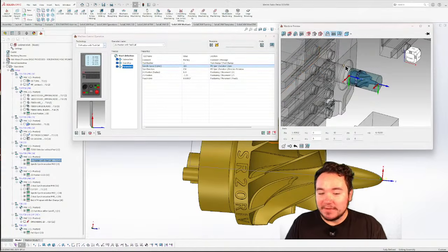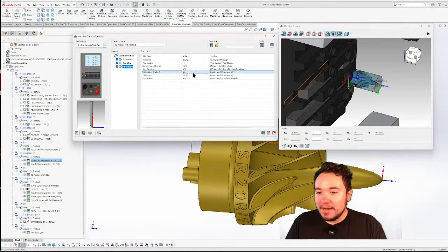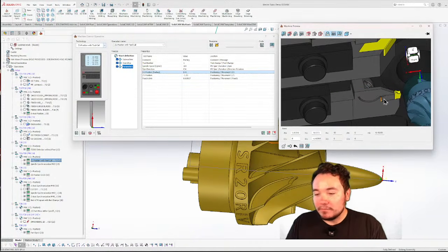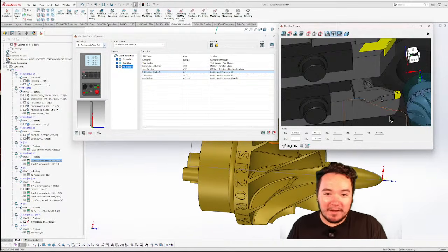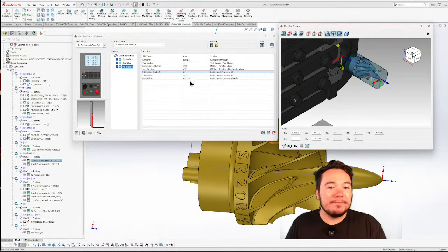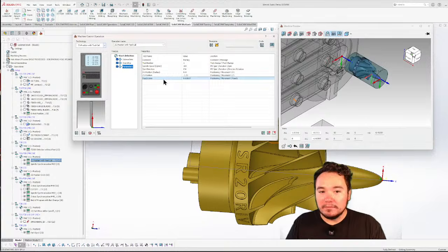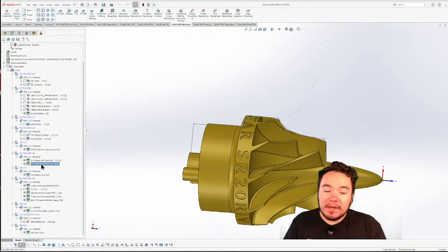Spindle speed, how fast the spindle is going to be spinning while the pickup is happening. Spin direction. Now X1 radius call out. So where is the X going to call out, or where's the X going to stop before the cutoff? So you have that starting right there. And then Z1 position, the stick out of how far you want Z to come out, and then feed in for the positioning. So I'm going to go ahead, exit out of this, and now we have a spindle synchronization.